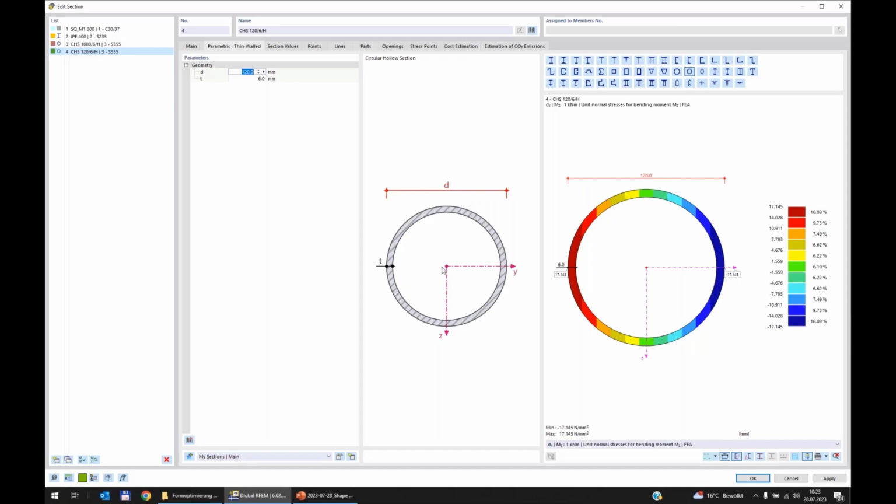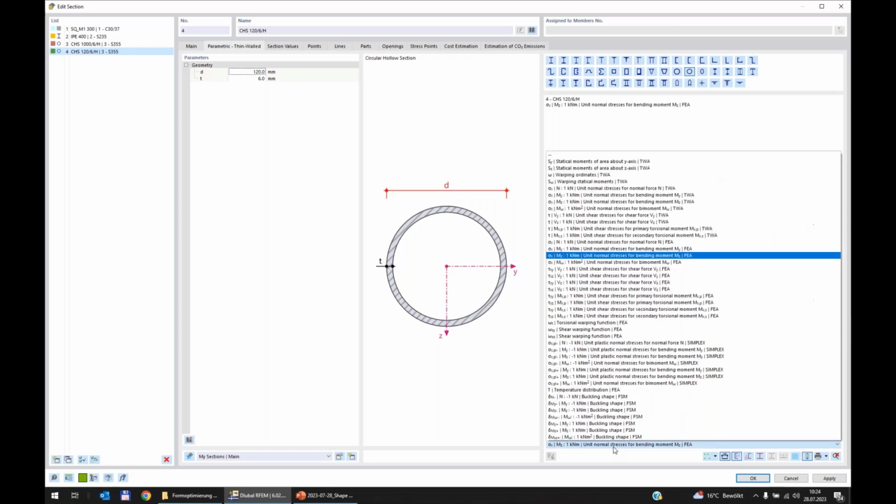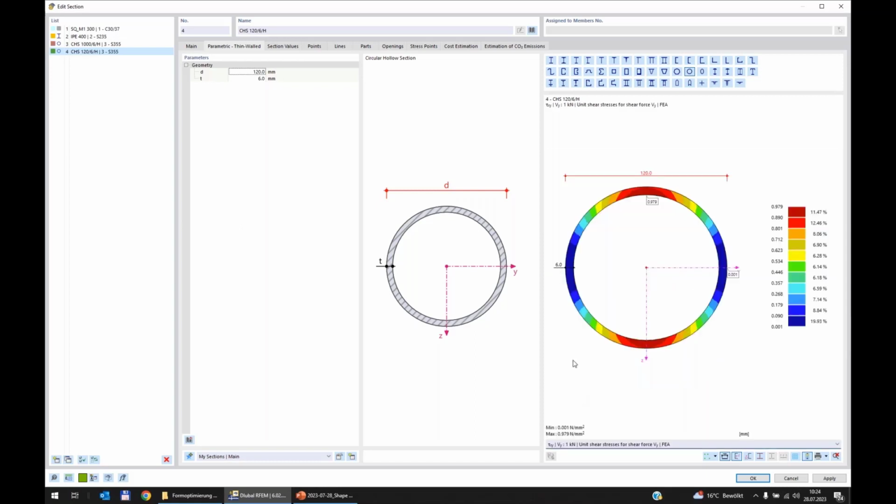So if we want to check shear force in Y direction, so open the scheme here. Shear force, where is it, UY in XY. Yes, then we see if I apply 1 kilonewton, I get a shear force of 0.9, almost 1.